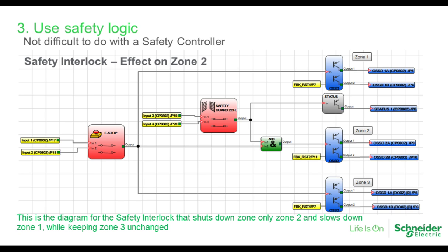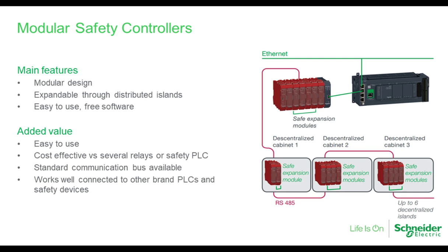So imagine, I don't have a diagram here, but could you imagine how different the wiring would be between the emergency stop shuts everything down scenario versus in some circumstances, I'm going to slow something down on this part, but the other part's okay, and I want to shut down this middle section. The wiring, if you were to just use relays, would be impossibly difficult, and you don't really want to do it. So you use something programmable.